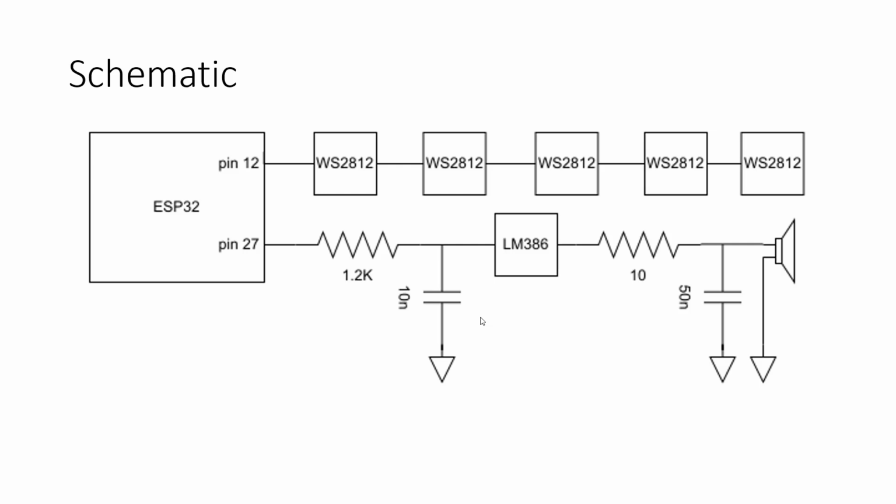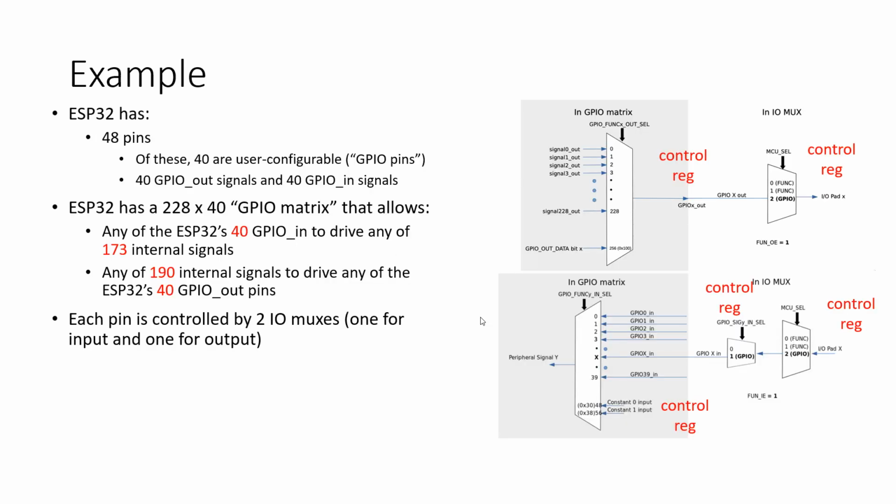Now, there's actually an additional capacitor, and there's also a trim pot that are on the board that connect to this guy. The trim pot is used to adjust the volume. You have to turn it through with a screwdriver. And the big giant capacitor is also connected to this somehow, but not related to this circuit, right? Okay, makes sense. So in total, there are 3 capacitors, 2 resistors, and 1 variable resistor, all associated with this audio circuit. I'm not showing them all here though, obviously, right? The big capacitor is to remove the DC component from this. Oh, okay. Gotcha.